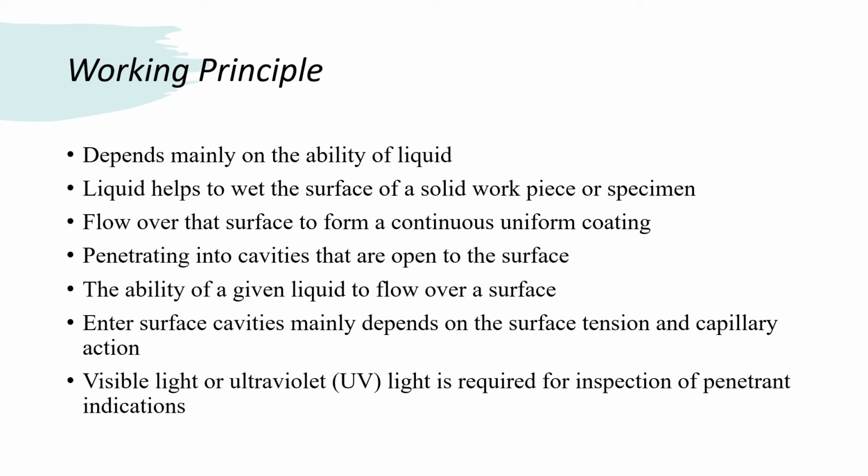Laser being a monochromatic light source, excitation by laser shows defect indication distinctly, both in form and color. However, use of the laser scanner is currently confined to laboratory testing and has not yet become applicable to in situ inspection of components in plants.